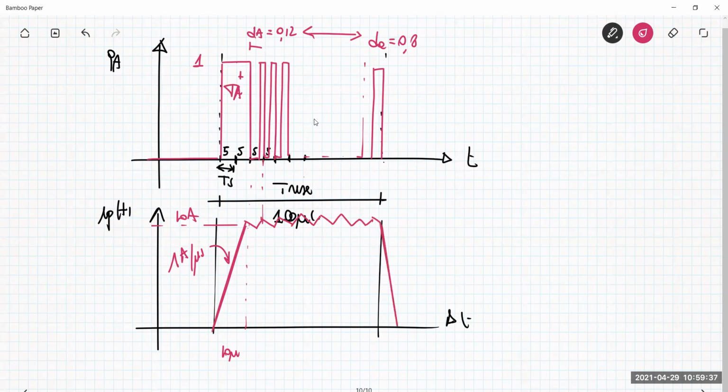As you can see, of course, we have some ripple in the phase in which the current should be constant. But then I have a characteristic which is much more similar to the ideal situation, to the case I'd like to have. What happens in this part? Here I am reducing the current. In order to reduce the current, I have both switches off.